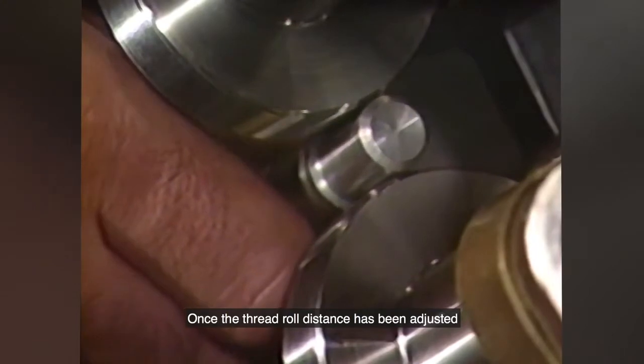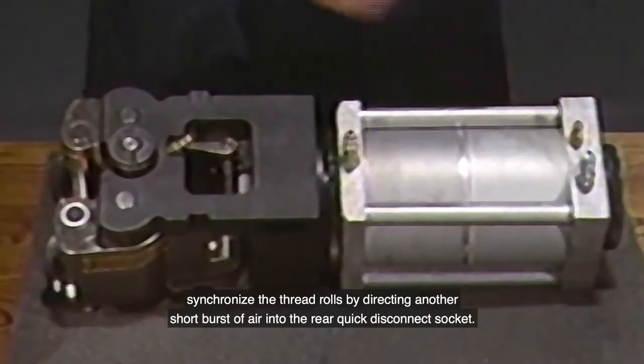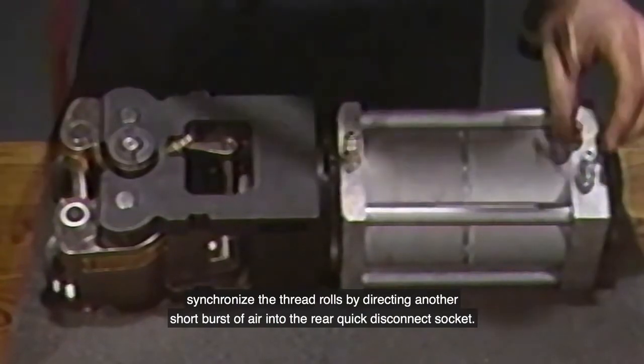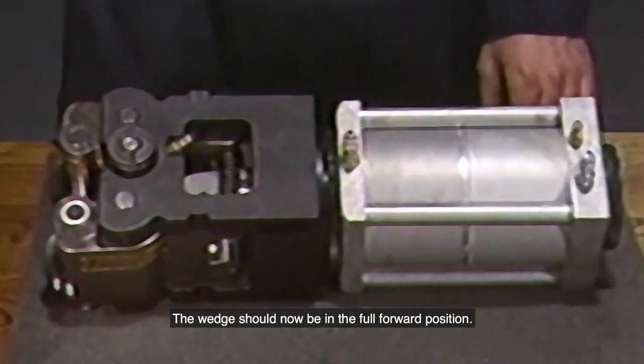Once the thread roll distance has been adjusted, synchronize the thread rolls by directing another short burst of air into the rear quick disconnect socket. The wedge should now be in the full forward position.